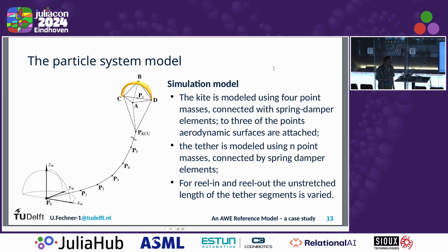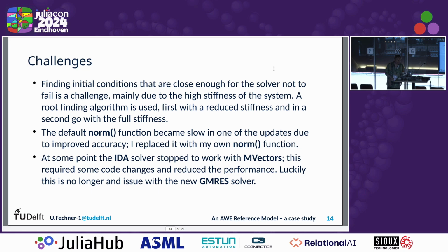And a little bit tricky is how do you implement the reel out and the reel in. And I do this by changing the unstretched length of the springs. And aerodynamic forces are attached to the points C, D, and B. So it's a kind of 3-plate model with pre-calculated lift and drag curves. And it works very well.